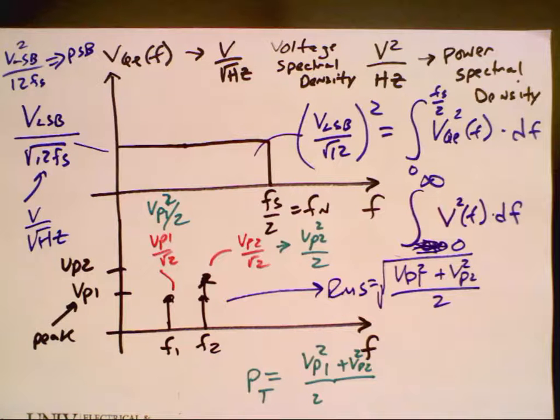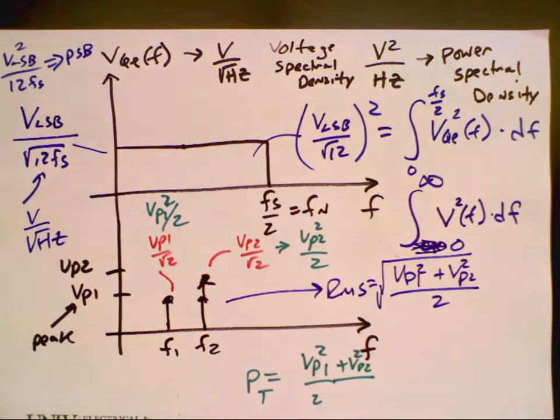I assume it's band limited between DC and F sub s, which is the worst case because all of the noise falls in my desired frequency band of interest. I also assume that my input is busy and the quantization noise is random. Then there's no reason that I'm going to have one value more than another or one frequency more than another frequency in this band. Does everybody follow that?